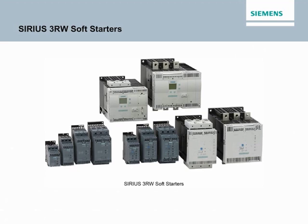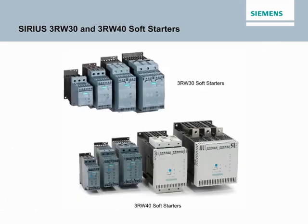The Sirius modular system includes Sirius 3RW30 and 3RW40 soft starters for standard applications and Sirius 3RW44 soft starters for high-feature applications. Sirius 3RW30 soft starters have an especially compact design that saves space and easily integrates with other Sirius components. 3RW30 soft starters are available for supply voltages up to 480 volts and operating current up to 106 amps at 40 degrees Celsius. Potentiometers on the front of the unit provide settings for ramp-up time and starting voltage.